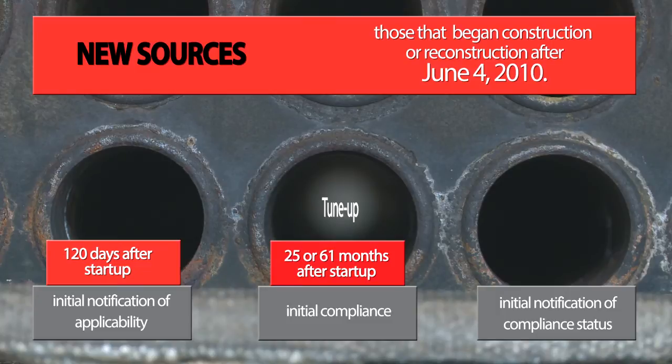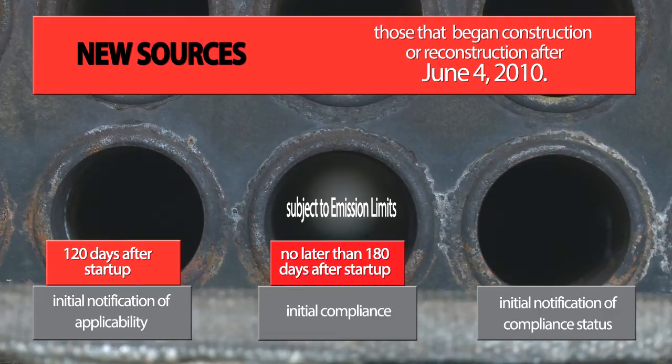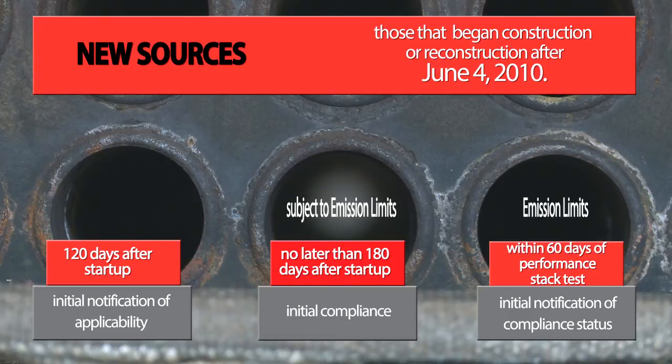New sources subject to an emission limit standard must demonstrate initial compliance no later than 180 days after startup and must submit initial notification of compliance status within 60 days of completing their performance stack test.